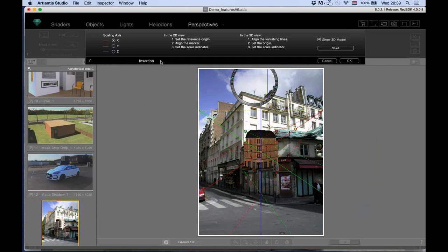The palette was completely reorganized and became simpler than previously. So the idea here is to set an XYZ coordinate system on a background. To place it, I'm just dragging the origin. And the same to do on a 2D image, and Artlantis will overlap them together. So just to set the XYZ coordinate on this background.